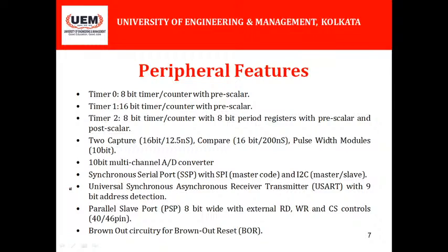The PIC microcontroller uses basically 3 major types of timer. First is timer 0. Timer 0 is an 8-bit timer or counter with prescaler. Timer 1 is a 16-bit timer or counter with prescaler. Timer 2 is an 8-bit timer or counter with 8-bit period register with prescaler and postscaler.